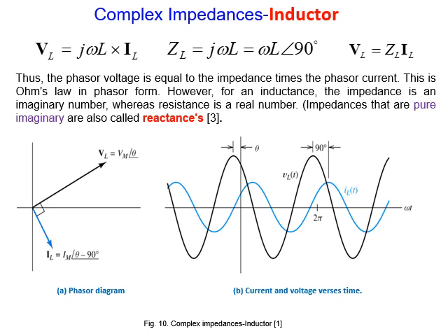Now, complex impedance, still with the inductor, we represented VL equals ZL IL. Now, if I want to sketch it, if this is IL, this is VL, sorry, Vm with angle theta, theta from here to here, which is the phase shift between the horizontal and the voltage. When we sketch the current, we will find that the current is delayed by 90 from the voltage.